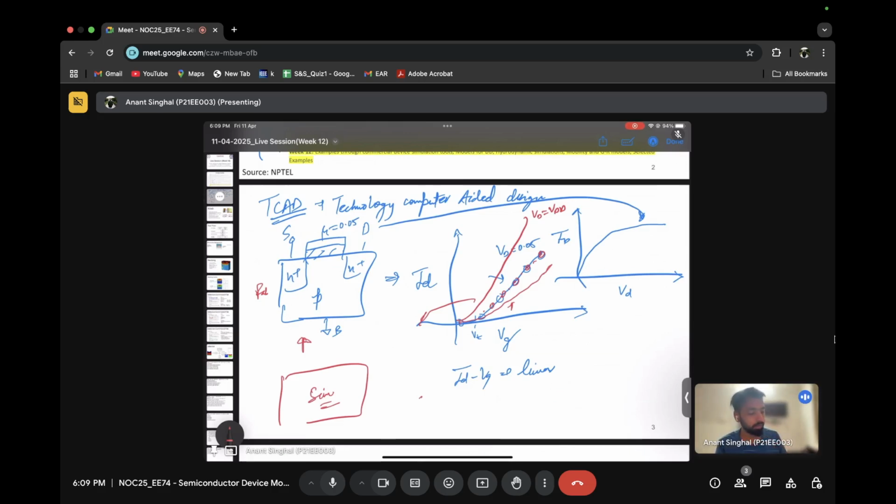So, for instance, if you remember, we covered short channel effects through the course, and we know there is a thing called velocity saturation, right? The velocity saturates because of this, and the current saturates. But due to channel length modulation, we have the factor 1 plus lambda VDS. Because of that, it does not remain exactly straight, but has a certain ID change. So you can see those parameters inside the TCAD, see which parameter is needed, and fit the fabricated data with the TCAD data.